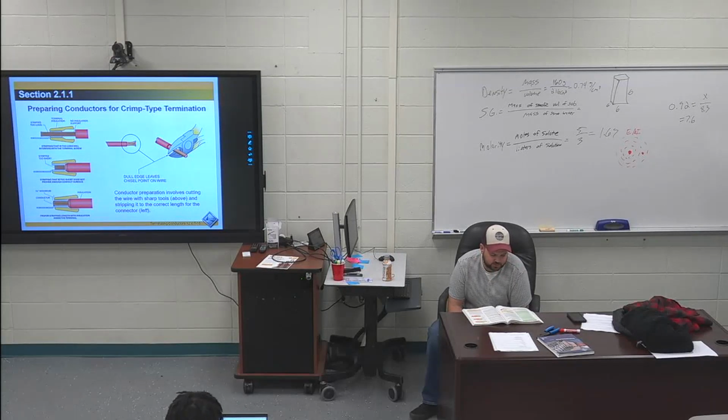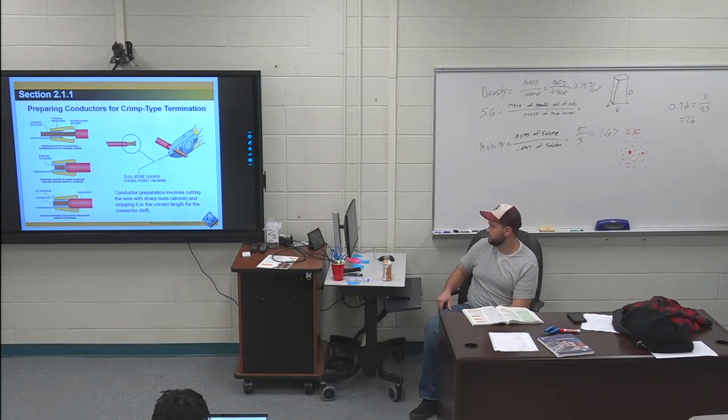Observe the following guidelines when stripping wire. So all the way at the bottom right of page 22, I've got that one bullet point highlighted. Avoid nicking, cutting, or scraping the wire strands, or insulation surrounding the inner conductors of multiple conductor cable. This type of damage to the wire indicates that the wrong stripping group of the stripping tool was used, the tool was improperly set or damaged, the wrong type of stripping blade was used, or the tool was incorrectly used. Seems like simple stuff.